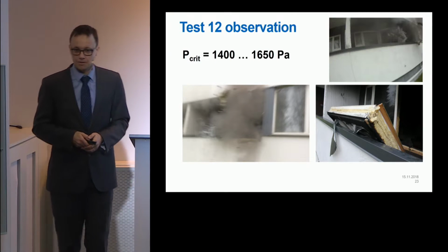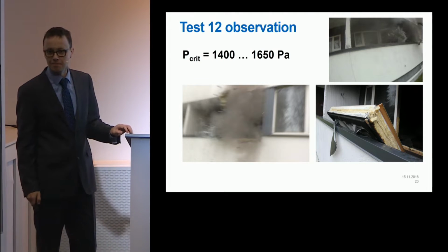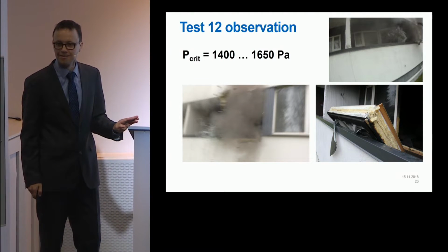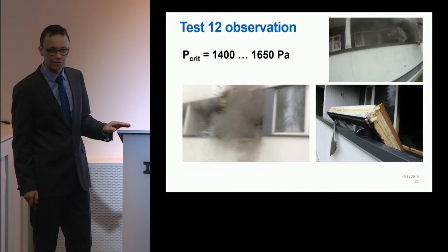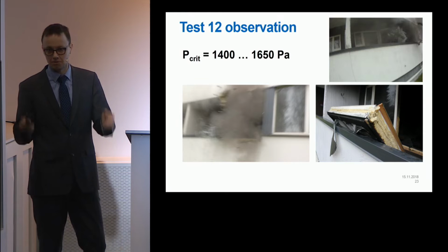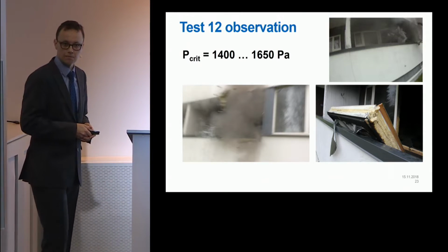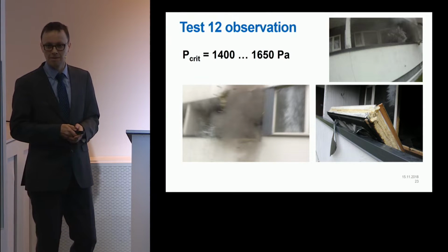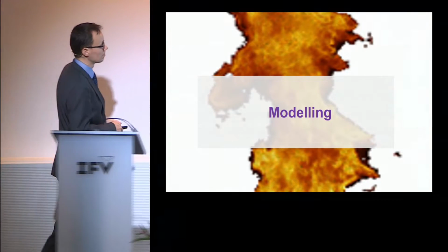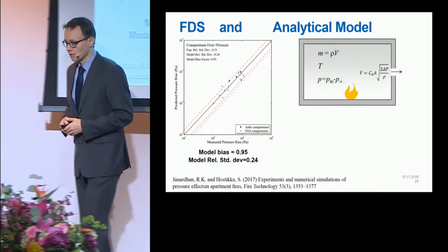Again, the construction workers had been a little bit quick. They hadn't used screws. They just used the polyurethane to fix that window frame in place, or at least it wasn't properly attached using screws. That can happen.